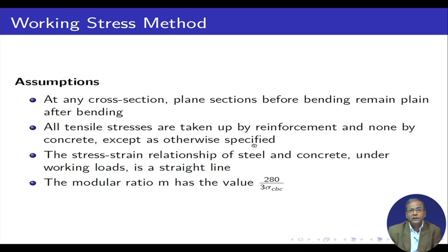If it is not specified, then we shall not consider the tension in concrete, because the tension in concrete is almost 10% of the compressive strength. So, we can neglect that portion, and compared to the amount taken by the steel, that will be negligible even if you consider it, and that is why we shall not consider it. And further, we consider the section as a cracked section. We shall come to that particular one, the cracked section for concrete.